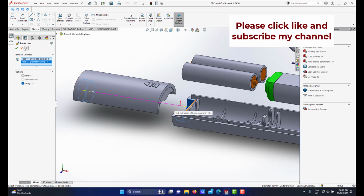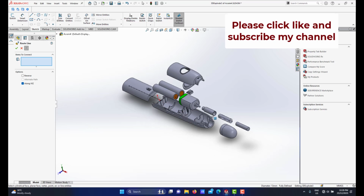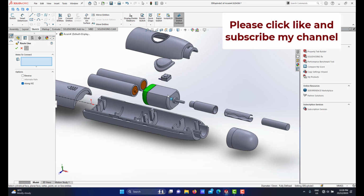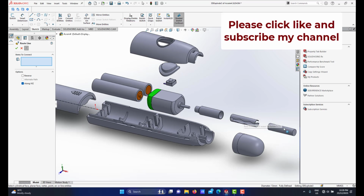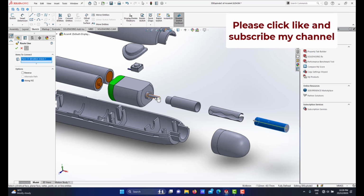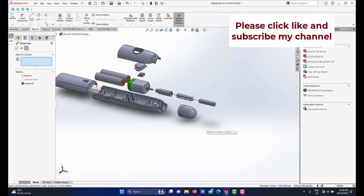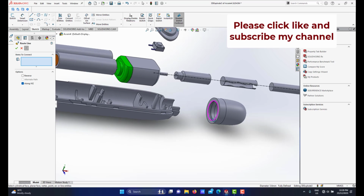All right, then I click OK. Okay, there is the line. I go for the easier one. This one I can also do for the shaft, since the flow of the assembly is from the rubber eraser to the gripper to the holder and to the shaft. So I can use the cylindrical surface up until here. As you can see, we have the path line. I click OK. And the next one should be this.